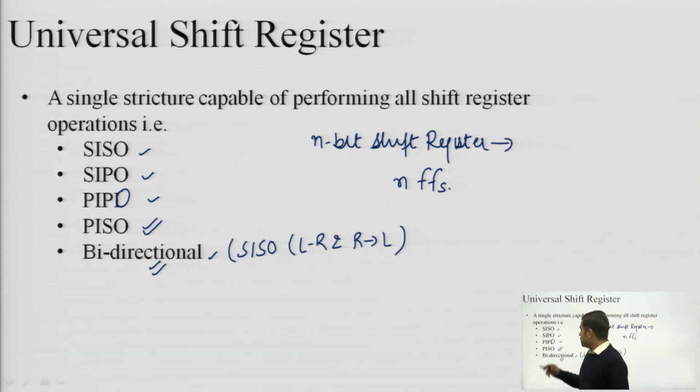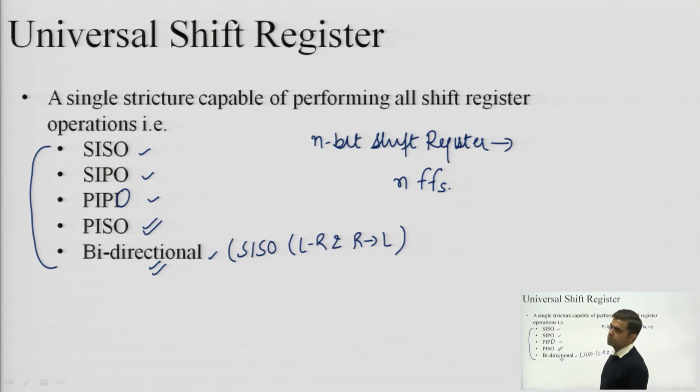So in the case of the universal shifter, we have to isolate all these 5 functionalities, which further include left to right and right to left ones. So this is going to be a very complex task, and in addition to flip-flops, this time a 2x1 multiplexer will not be sufficient. We will be using a 4x1 multiplexer instead, and instead of placing the multiplexers between the flip-flops, we will be placing them separately above the flip-flops, with a different alignment of the flip-flops and multiplexers. So let's cover that topic and the circuit.